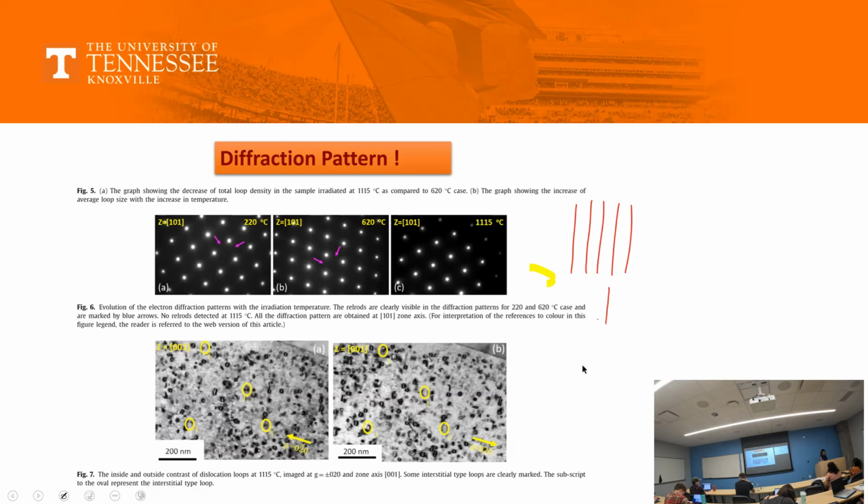Because you have added this half plane, you get a kind of pattern like this. Remember, this was told to you as an edge dislocation. Now this dislocation starts to move in the plane in one direction, and the direction in which it moves is known as the Burgers vector. This half plane is completely getting translated.